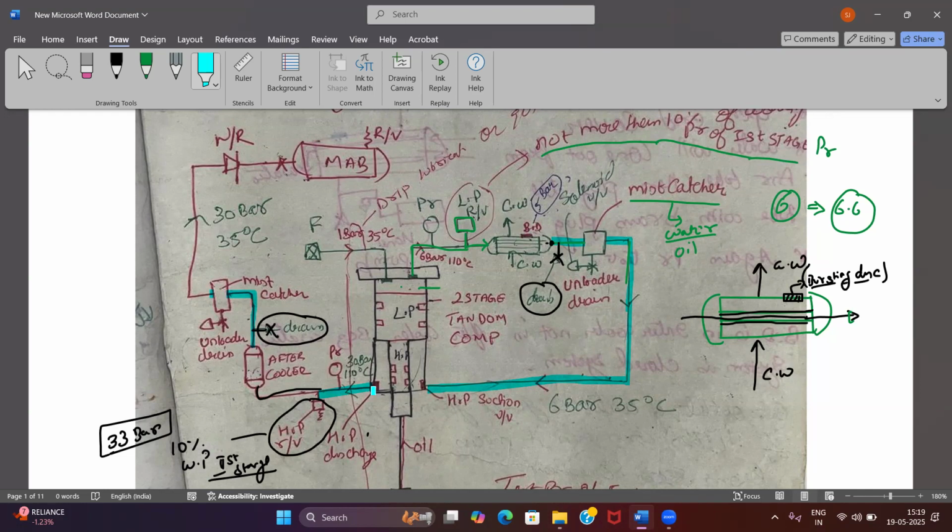air is going to increase. Okay. Yes, sir. Like if you talk about the air cooler in your main engine, we say it increases the density of the air, right? Yes, sir. So if it increases the density after cooling, and I'm removing the unwanted parts like your moisture and your oil, I can store a much larger amount of air. Obviously, the density has also increased. I can store much more quantity of air inside my air bottle.